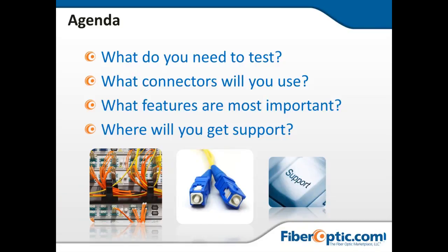So what you will need to perform your test, what type of connectors will I be using? Whether they're SC, as pictured on the screen here in the middle, you need to make sure you have the same connection when you're connecting to the OTDR, or at least your launch box. Really, it would be your launch box in this case, and we'll get into that in more detail. But what connectors do you have on the end of your fibers? The fiber under test is going to be an important thing.